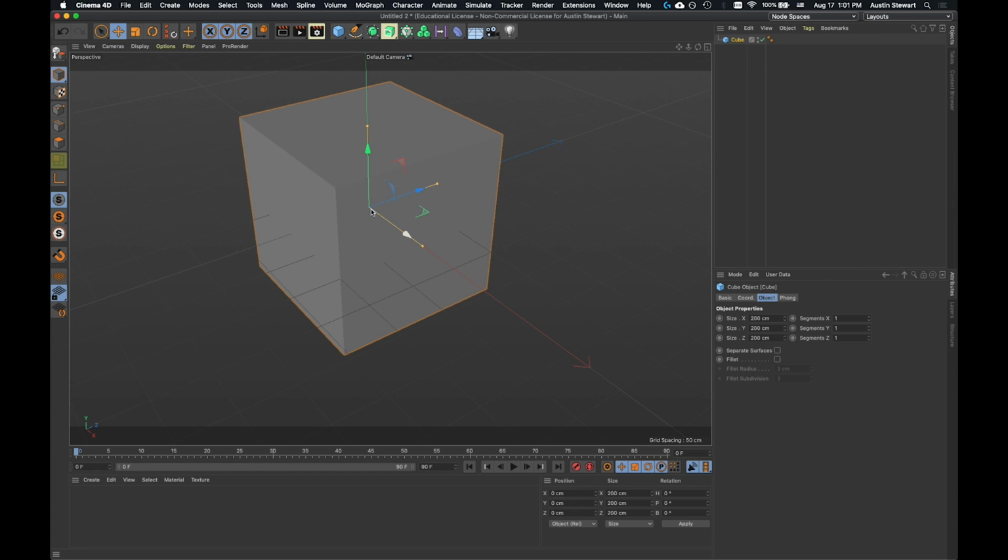And what that means is that right now, when I created this object, the point where all 3 of these things come together, and that's these lighter colored, longer arrows, where they come together, that is called the origin. It's the center of this virtual world. And it is value 0, 0, 0. It means that it's centered along the x, y, and z axis, right? So the z-axis goes from 0 to infinity in this direction, and 0 to negative infinity in the other direction. The x-axis does the same thing along this red arrow, and the y-axis does the same thing along the green.